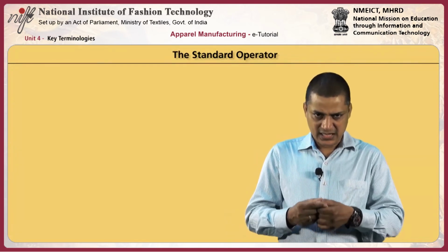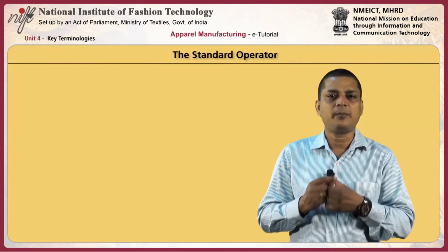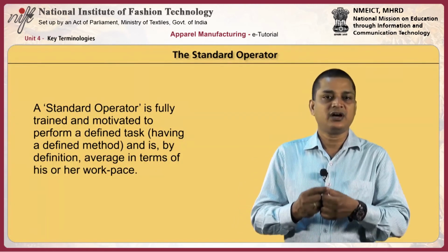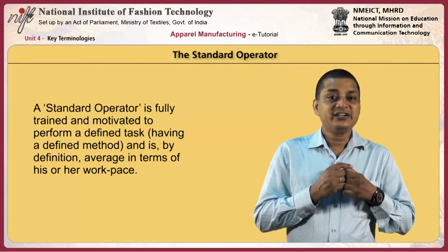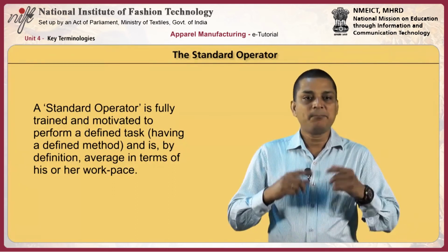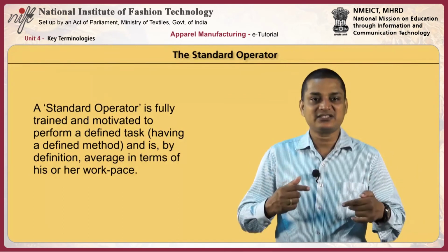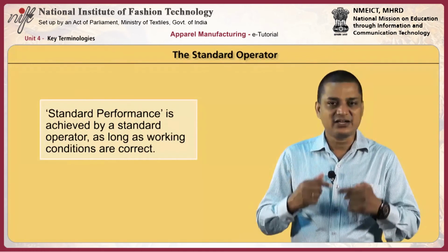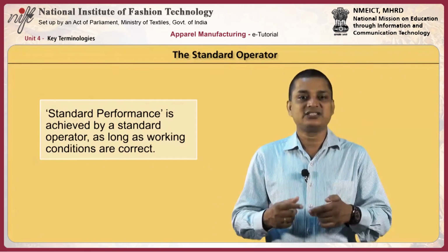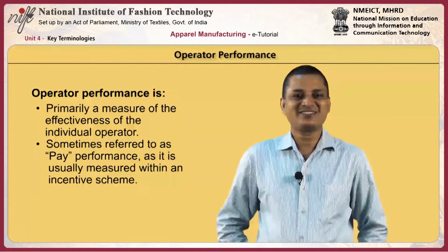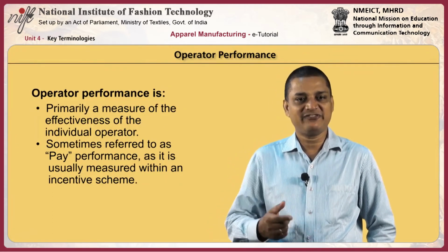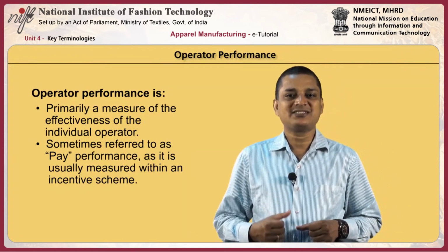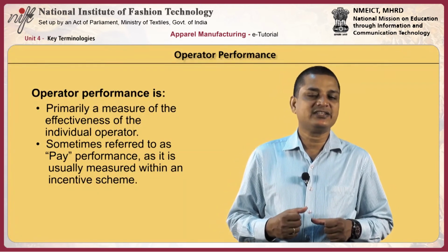Time study professionals apply the concept of a standard operator. A standard operator is fully trained and motivated to perform a defined task, having a defined method, and is by definition average in terms of his or her work pace. Standard performance is achieved by a standard operator as long as working conditions are correct. Operator performance is primarily a measure of effectiveness of the individual operator, sometimes referred to as pay performance, as it is usually measured within an incentive scheme.